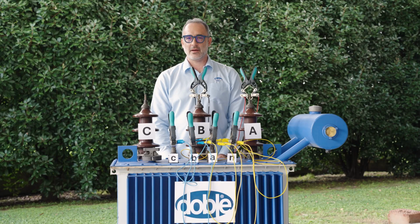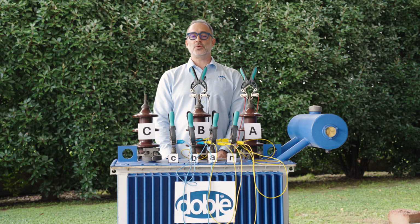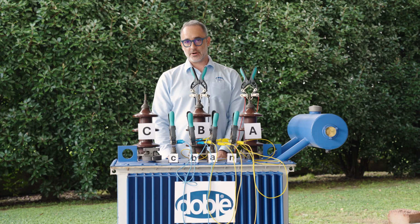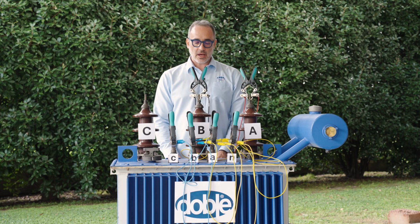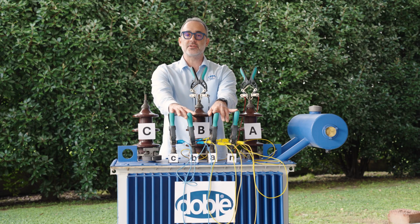Welcome back. As I mentioned before, the short circuit impedance test is a test which we do in order to measure the losses in copper, a certain percentage. How do we execute the test? The secondary side is short-circuited.